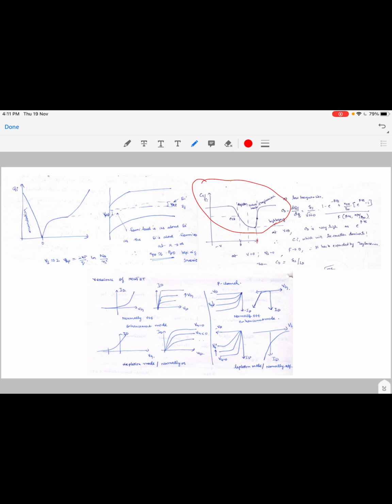And you can typically have two kinds of MOSFET with this inversion. You can have an N-type MOSFET or a P-type MOSFET. You can have an inversion to begin with and then deplete it to turn it off, or the other way around. So there are 4 different configurations in which a MOSFET exists. And then we saw several output characteristics and such. We spent much less time on the MOSFET in comparison to the BJT and PN junction diodes, because there are dedicated courses on MOSFETs, whereas this is supposedly the course dedicated to diodes and BJTs.